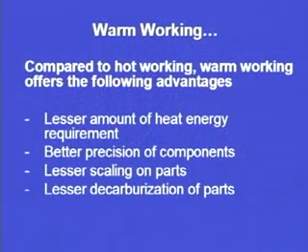Now, warm working compared to hot working also offers certain advantages. What are these advantages of warm working as compared to hot working? A lesser amount of heat energy is required because we are only slightly elevating the temperature, we are not going beyond the recrystallization temperature. Better precision of components is there.